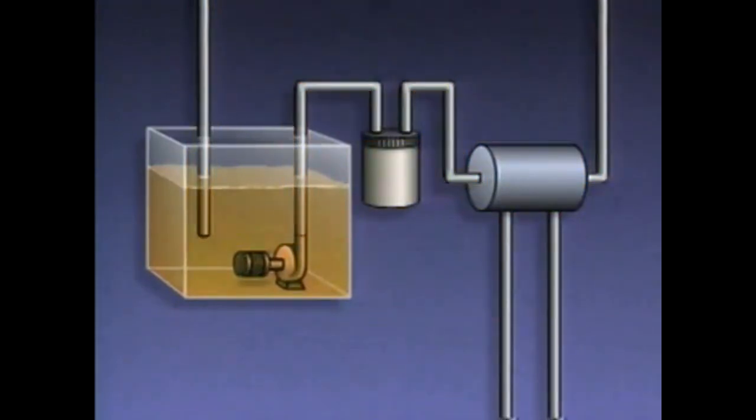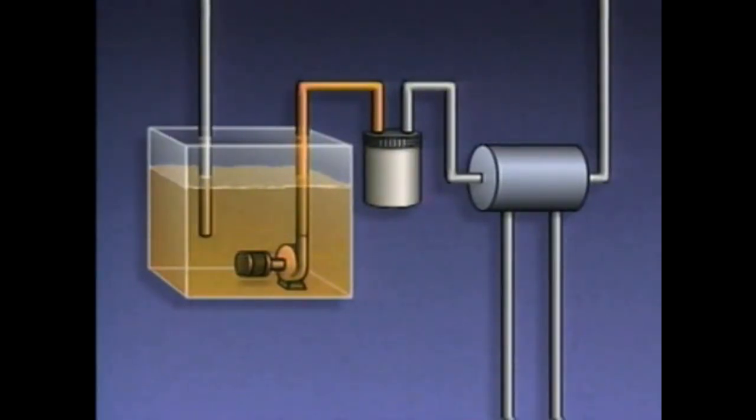Oil for the lubrication system is stored in the reservoir. During operation, the pump draws oil out of the reservoir and moves it through the rest of the system. A screen on the pump traps large solid particles and debris. From the pump, the oil goes through the oil filter, where dirt and other smaller particles that were able to pass through the screen are removed. If these materials are not removed, they can get into the compressor's moving parts and cause damage.